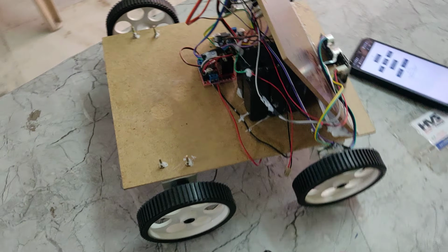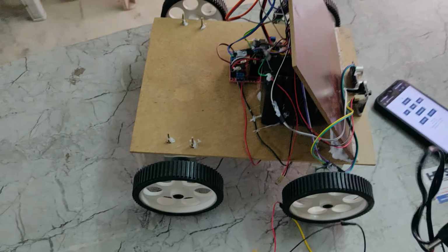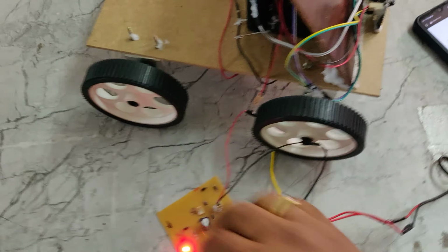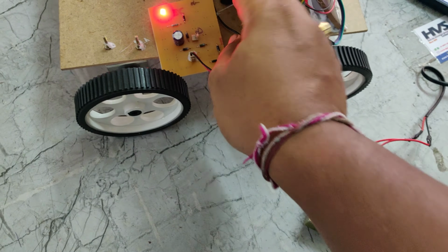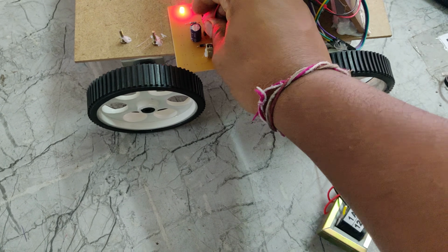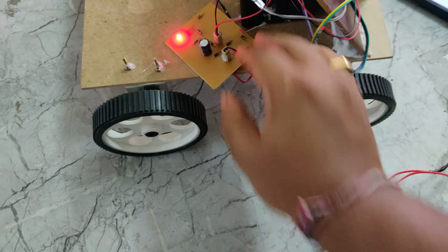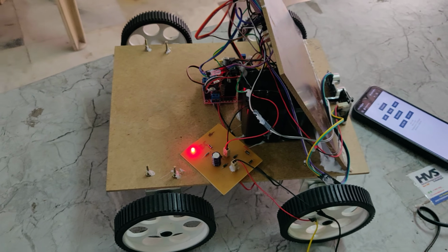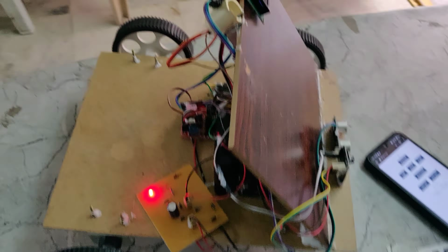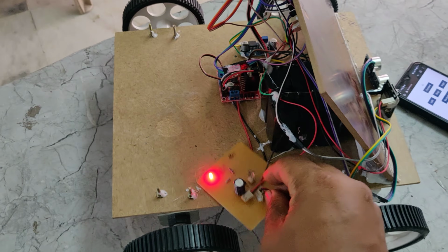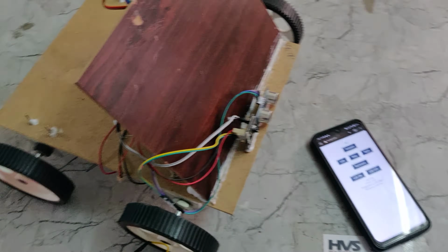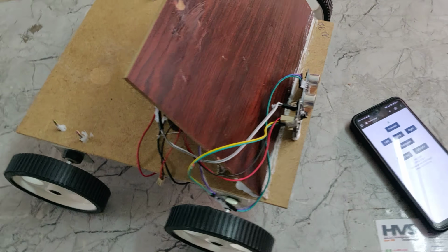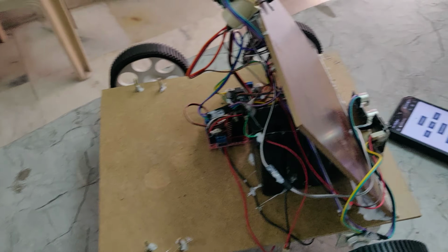Before the demonstration, we need to charge the battery fully, so we are providing this charging circuit. Switch on the power supply to this transformer, and next connect these two pins at the battery slots. Now we can see the light indication that the battery is charging. It will take around 5 to 6 hours to be fully charged. Until then we should keep the battery under charging, and after that the charging circuit will automatically block the current flow to the battery once it is fully charged. So the first step is to keep the battery under full charge.